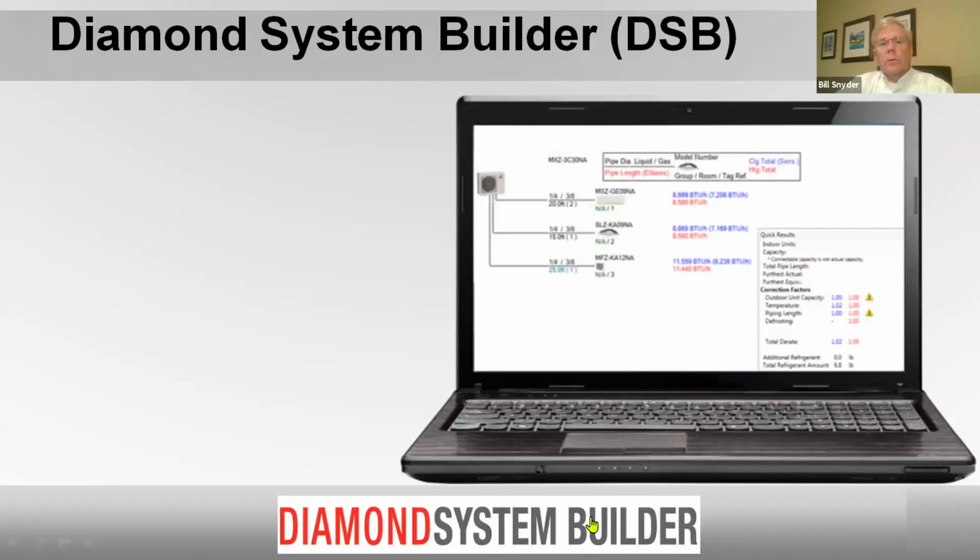Diamond System Builder is a free program that you can download from mylinkdrive.com. And literally, on this side, you drag stuff across and drop it on here. So you pick your outdoor unit, you pick all your indoor equipment, and it tells you the line sizes, like 1/4 and 3/8, 1/4 3/8, 1/4 3/8 here. And it tells you its capacity based on, when you first set this up, you pick your area.